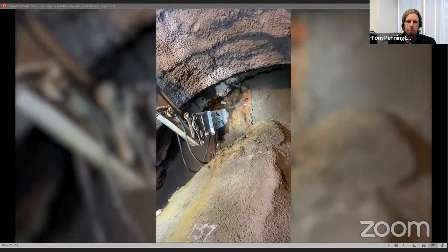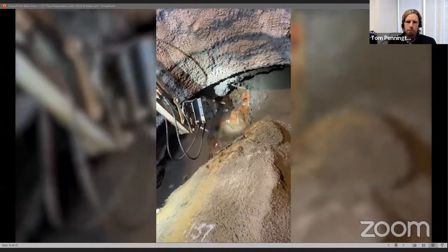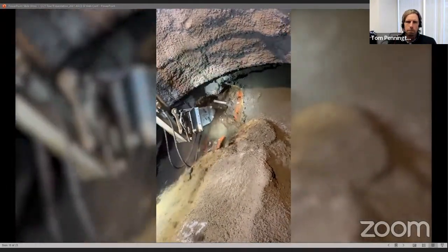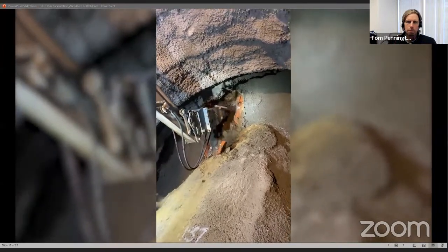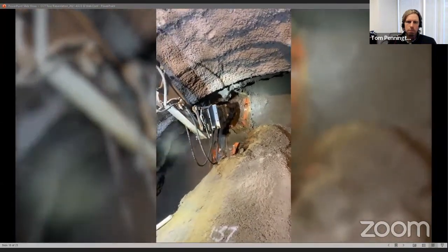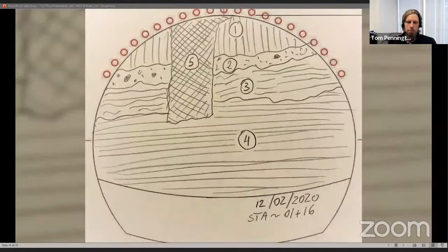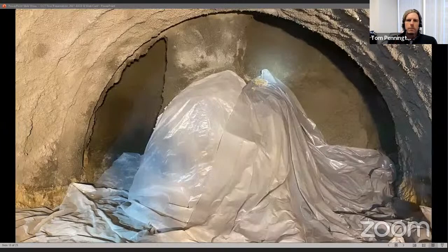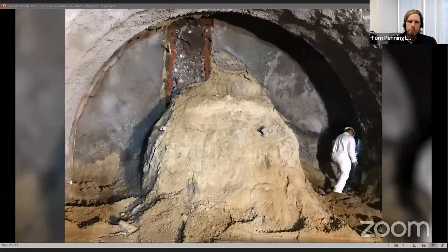Once the excavation had advanced to within 15 feet of the observed brick location, probe holes were drilled to investigate the size and location of this brick anomaly, and more soil samples were tested. This anomaly was suspected to be a decommissioned brick-lined well turned into a trash pit, a feature known to exist in downtown San Diego from previous excavations.